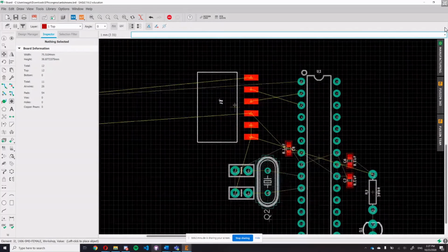And just something to add there, as we chose the components, like for example the decoupling capacitors, you saw numbers like 0603 or 0402, and these are just the inch indications of the dimensions of the sizes of the components. If you see the capacitors, they are pretty small. The 0402 or 0603 is just an indication of the size we chose. Yeah, thanks. And now what?